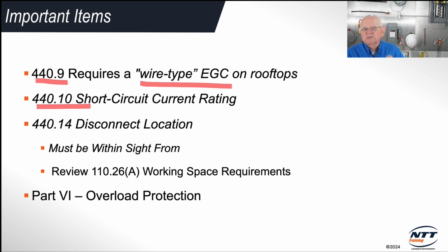So what we typically see, that value is not on there, simply because they feel like there's not enough available fault current that the equipment would be a problem. Whereas if we're in a large commercial industrial type application, office buildings, all of that, we could have a lot more available fault current available. So it's required to be marked on there.